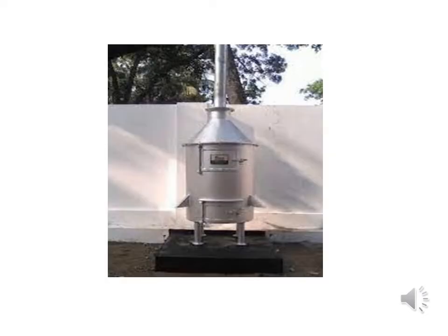Now we can see the different regions present inside this equipment. This is a typical representation of an incinerator which is used for the conversion of waste to energy. This incinerator contains mainly 4 regions. First one is the drying region, second one is the pyrolysis region, third one is the reduction region, and final one is the oxidation region. The drying region is present on the topmost portion of this incinerator.